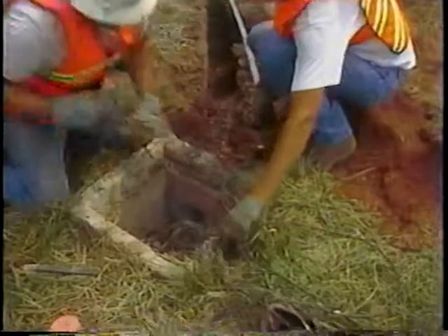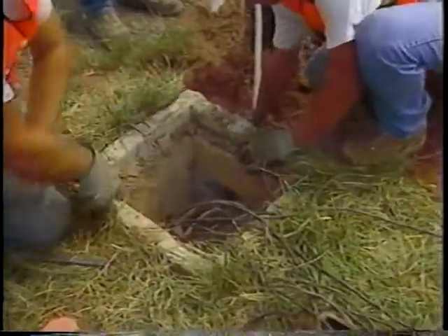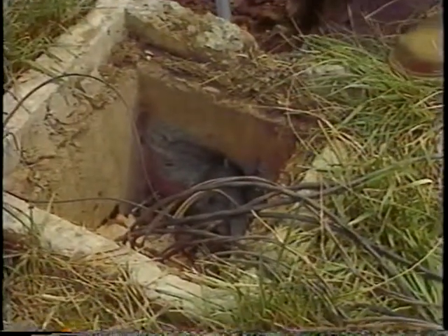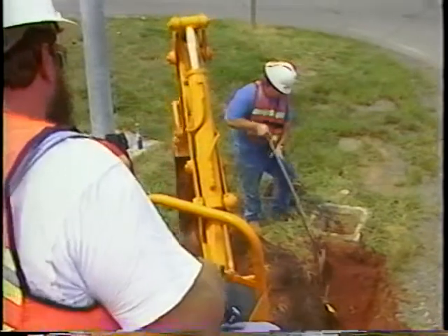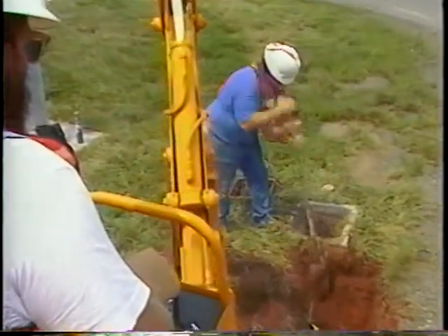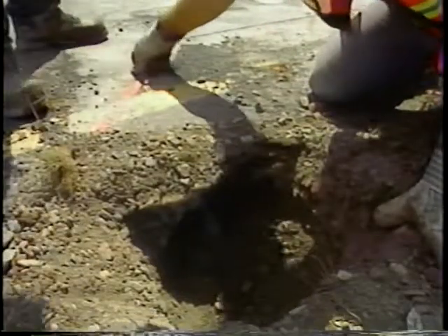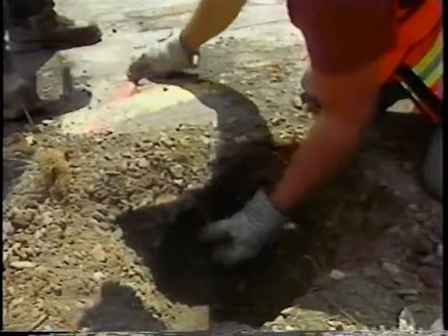Most installations utilize a standard number 3 or number 5 pull box. For our example, we are using an existing number 1 pull box. The conduit, usually a 1-inch conduit carrying 1 or 2 twisted wires, is connected to the pull box during its installation. At the roadway end, the conduit should be terminated 2 inches below the pavement surface.